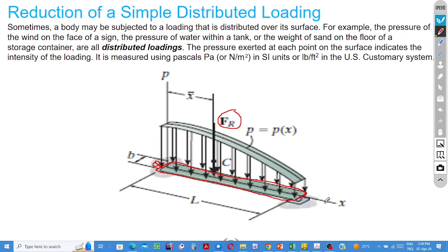In finding the equivalent system, or the resultant of the given force systems, we must consider the translation effects and also the rotation effects. How? Add the forces up, find the resultant, calculate the rotation effects, the moments with respect to a reference, and then add the moments up.